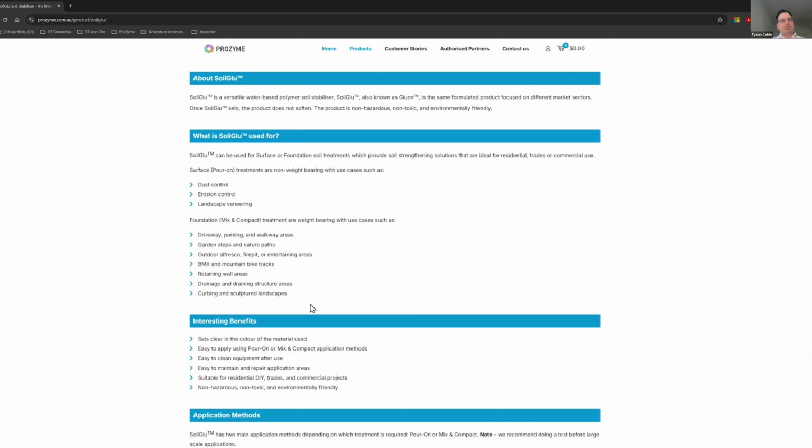You've got to get the right type of soil distribution. So you want to have sub 10 mil. You can have higher than that. You can have inch size aggregates in there, but it can't be many. And you want to have most of it being somewhere between fine size of sand and up to small pebbles in a nice distribution curve for a foundation treatment. That means that the soils are nicely able to fill each other's porous spots and create good basic structure just in the soil grains themselves.